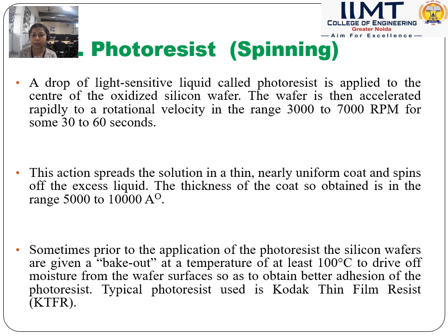then the wafer is accelerated rapidly to a rotational velocity in the range of 3000 to 7000 rpm for some 30 to 60 seconds, and this action spreads the solution in a thin, nearly uniform coat and spins off the excess liquid. The thickness of the coat is obtained in the range of 5000 to 10,000 angstrom.